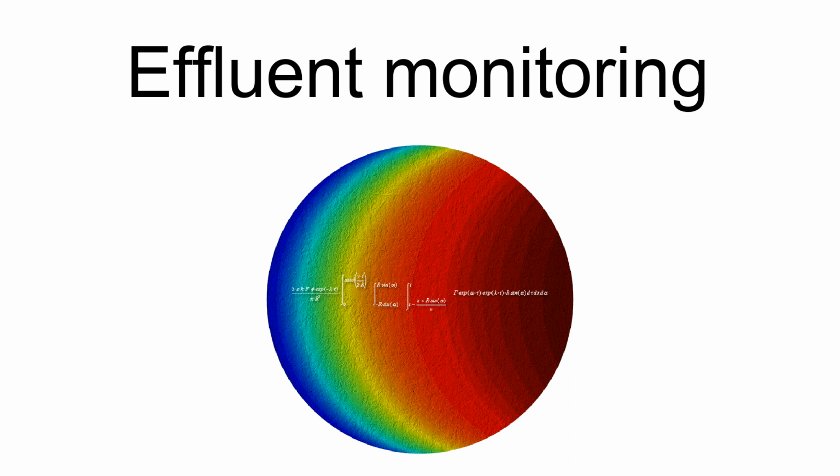In effluent monitoring, a sample of the air in the plant stack is withdrawn and pulled down to the CPAM location. This sampled air in many cases must travel a considerable distance through piping. Extracting and transporting the particulates for the CPAM to measure in such a way that the measurement is representative of what is being released from the facility is challenging.